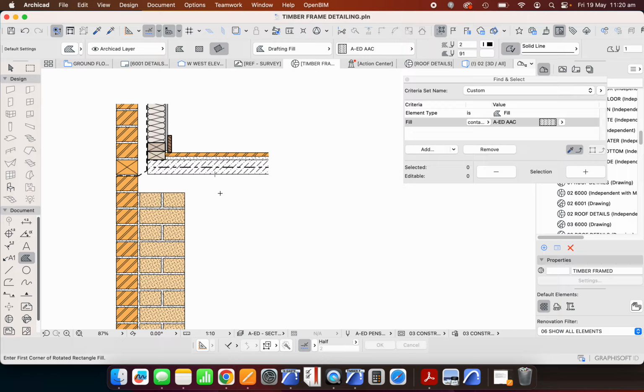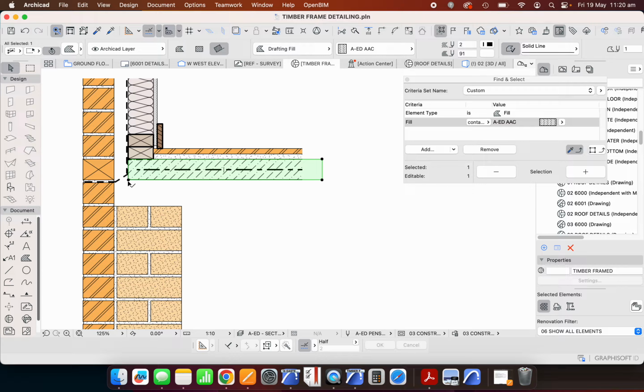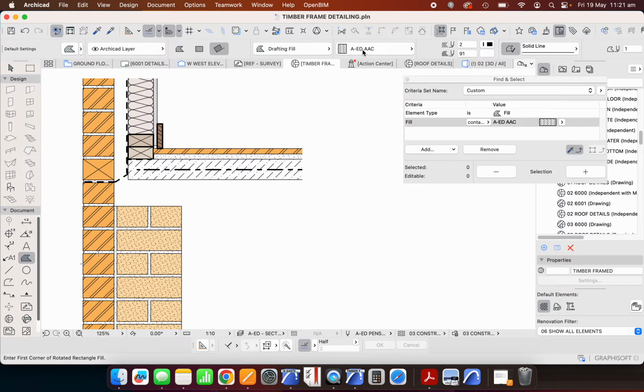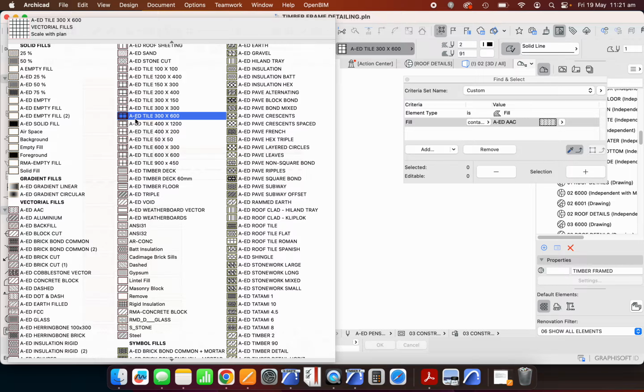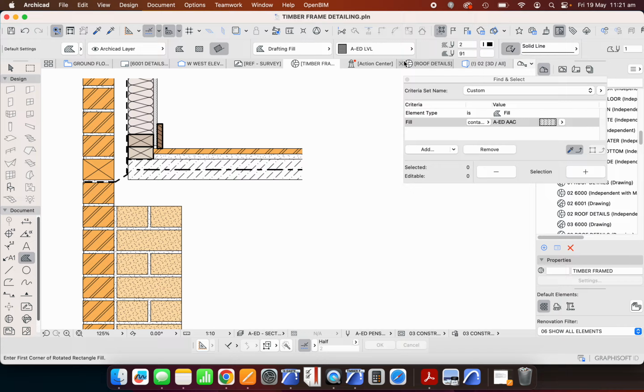All right. Underneath my power panel, so this is my structural floor sheeting, we could call it. It's a panel, not really a sheet, but same sort of idea. We then have the joist. What am I going to use for the joist? I'm going to create the joist out of an LVL. So in my settings, AD LVL.